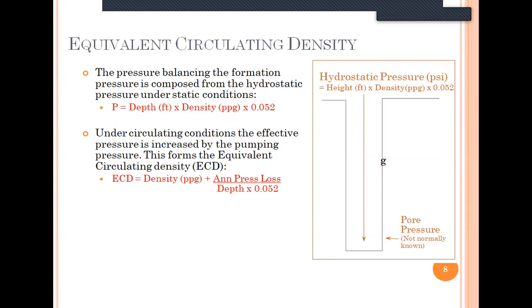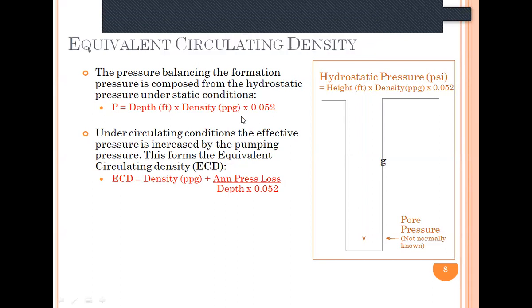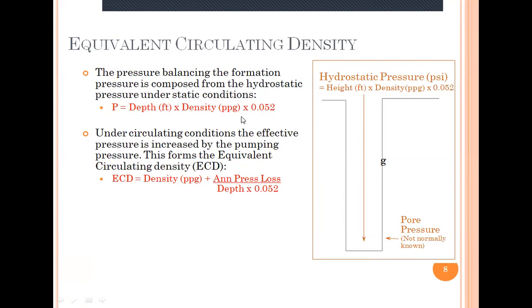So the ECD is a serious problem. If any of you read about the new technology, like PWD, MWD, and managed pressure drilling, we are drilling with a very narrow window and trying to avoid the ECD. So the ECD is a big issue and a serious problem.